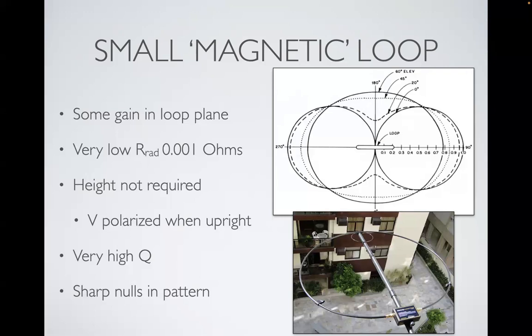And there's been some fun work that's been done with automatically tuning these things as you tune the transceiver. So it's not as much of a restriction as you might think, but still, there's going to be very high fields near these things, very high field density. It'll cook the paint off your walls sometimes. And you've got this capacitor with very high voltage on it. And that radiation resistance will kill you if you don't get it well connected.